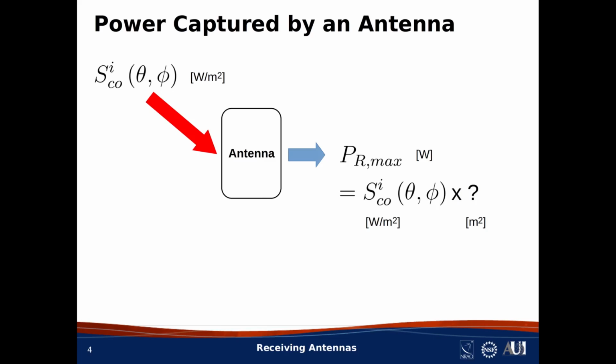The electrical engineers in the audience will know that this condition can be achieved when the receiver is conjugate matched to the self-impedance of the antenna. However, all we need to know now is that everything is set up for the maximum possible power transfer from the antenna to the receiver. So, just to summarize, remember that the equation that we are developing applies to the case where we have both a fully copolarized incident wave and perfect conjugate impedance matching with the receiver, so we have maximum power transfer.